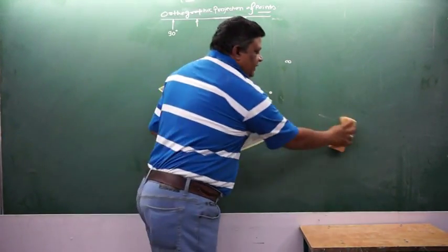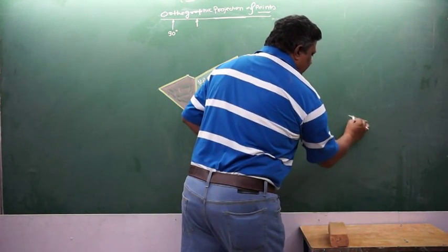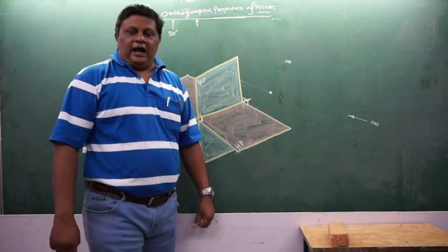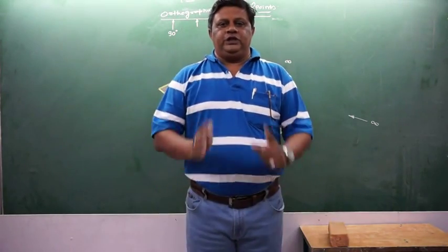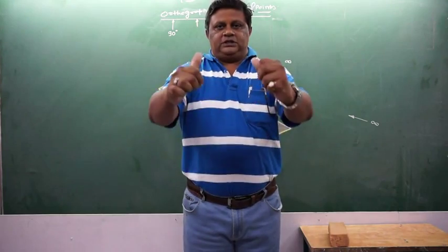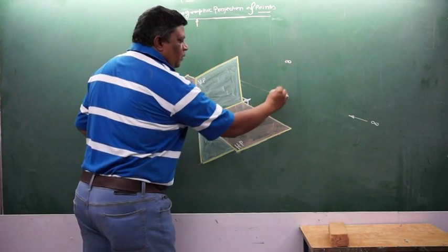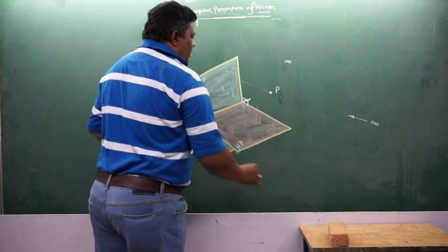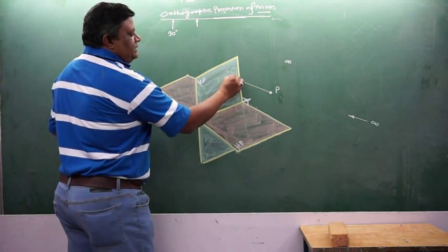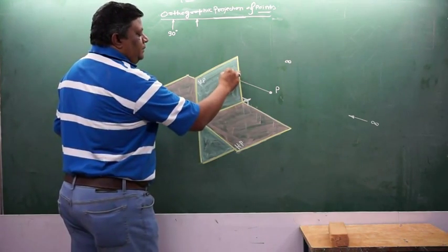So, if this observer is there, he is standing at infinity and observing this object as you are standing out there. Now, if you see me from the front, what do you see? This is the front view of me coming. Similarly, the representation of this point, which I represented by capital P, is going to take place on the vertical plane as P, represented by small p dash.